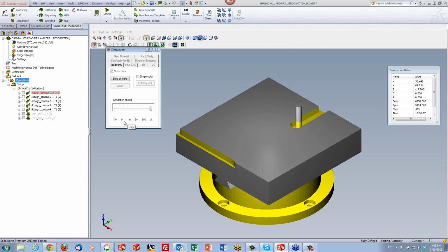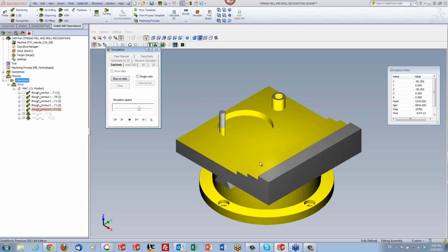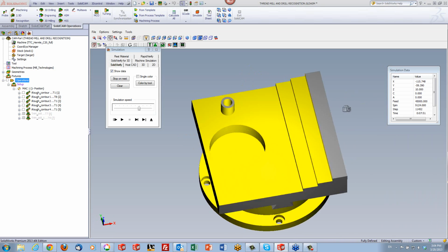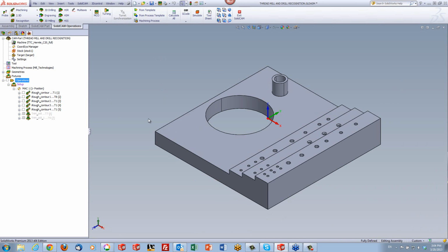And as you can see, it's doing the iMachining toolpath on the first area. Let me slow it down just a touch. Creating this area, then working in a morph spiral in this area over here, then cleaning out this hole. The steps. Basically, we're ready now for my drill recognition as shown over here. I have all my material milled out, and we're going to start with the drill recognition. Okay.